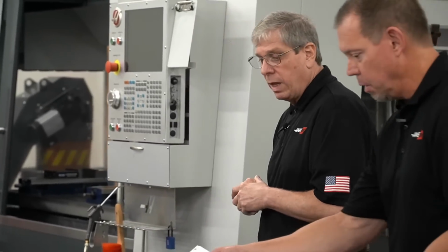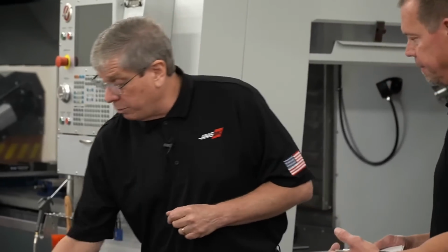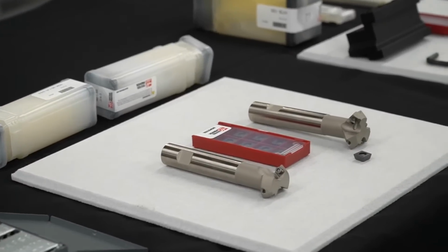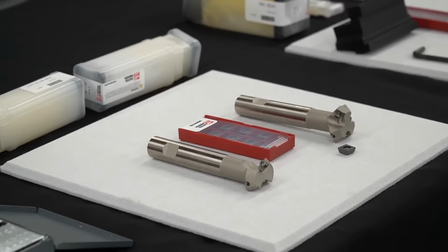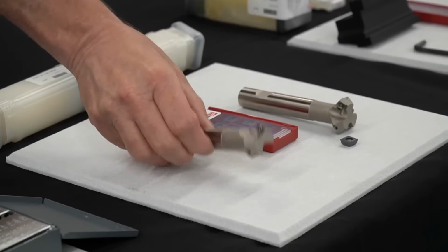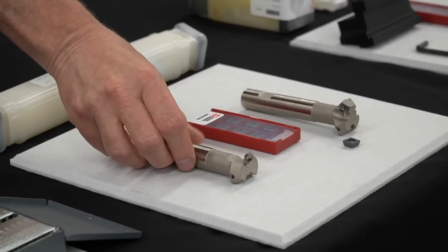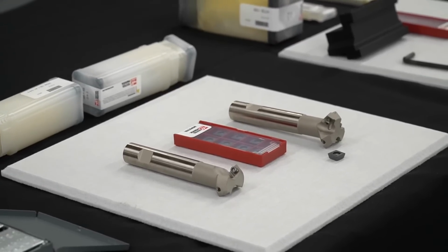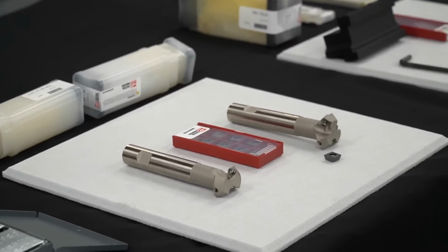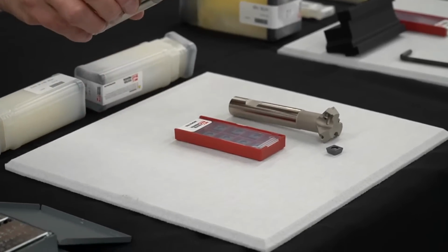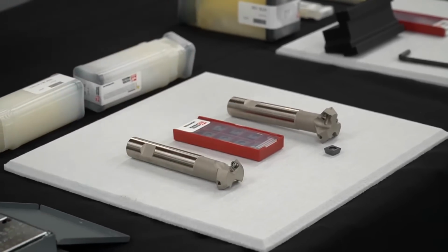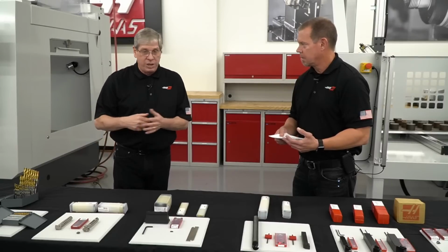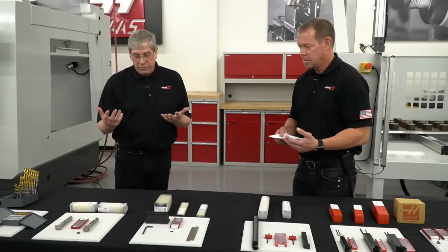Okay, moving on. Chamfer mill, inserted chamfer mill. Every good machine shop takes all the sharp edges off of the part in the CNC machine before the part comes off. So these are fantastic. There's a 2-flute and a 3-flute version of the chamfer tool. These are great for obviously chamfering the top edge of a part, but with the relief angle on the shank, you can get to the bottom and chamfer the bottom edge of a part before it comes off the machine.